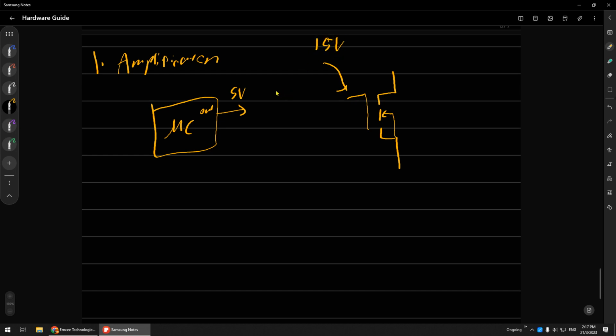So you can see here, this is the reason you need the gate driver or gate drive, because the voltage is not enough. To switch the MOSFET or IGBT you need 15 volt, but the microcontroller only has 5 volt. So that is one for voltage.